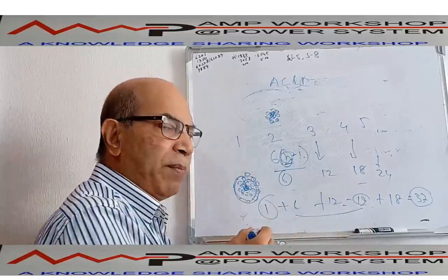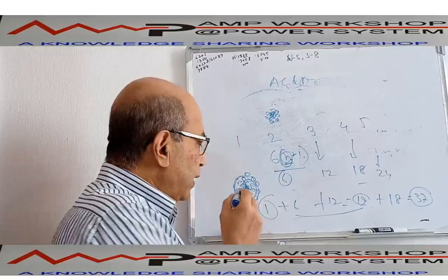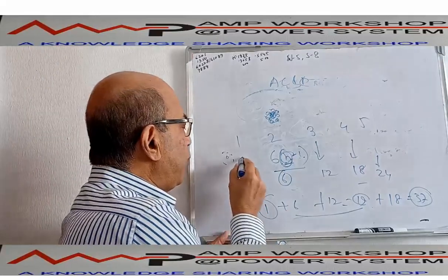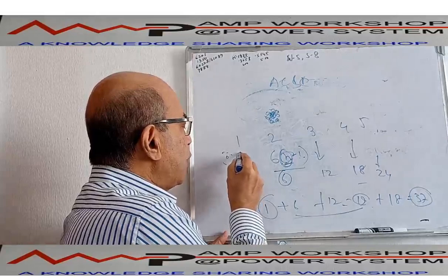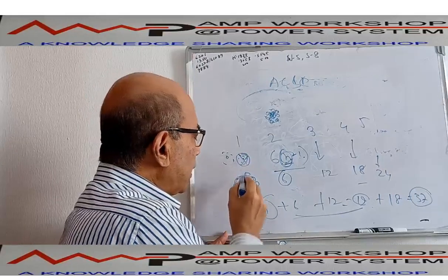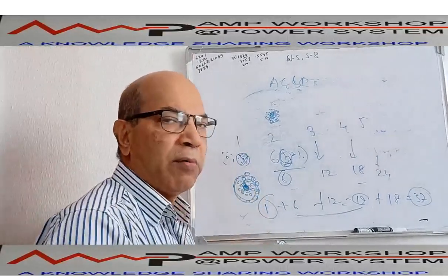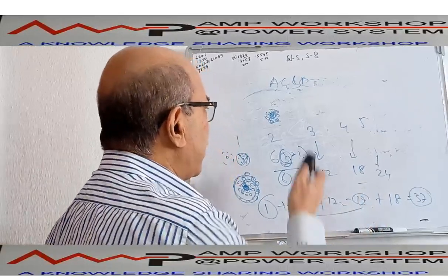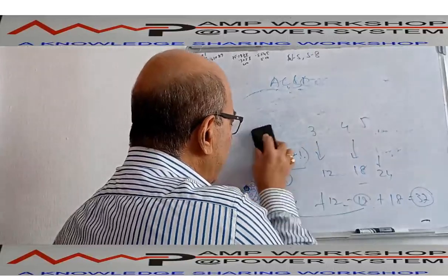But sometimes, to increase the reinforcement, the center conductor itself can consist of multiple strands. It may be one center conductor with 6 on the outer side, total 7. That makes one conductor that we put at the center. That is also sometimes possible. Suppose we make an ACSR conductor or any type of conductor.